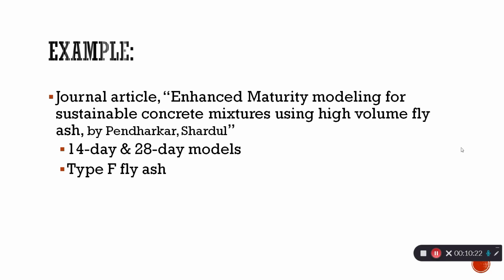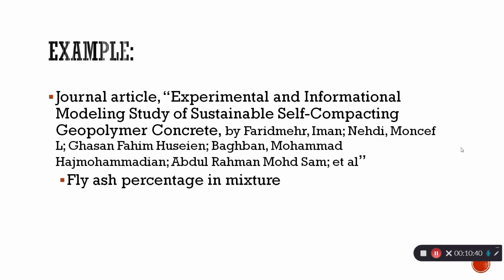The 35% of type F fly ash and the 50% of type F fly ash using the 14-day maturity model predict higher values of in-place compressive strength. The mixtures with 35% and 50% of type F fly ash have more accurate estimates of in-place strength for the 14-day maturity models than the pull-out correlations. A second example comes from the journal article Experimental and Informational Modeling Study of Sustainable Self-Compacting Geopolymer Concrete.